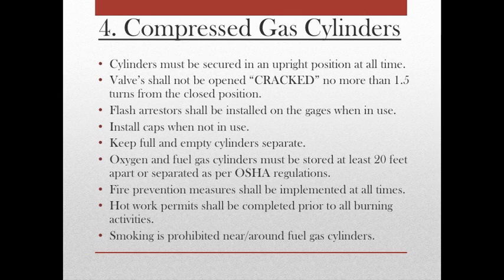Fire protection measures shall be implemented at all times. Hot work permits shall be completed prior to all burning activities. Smoking is prohibited near and around fuel gas cylinders.